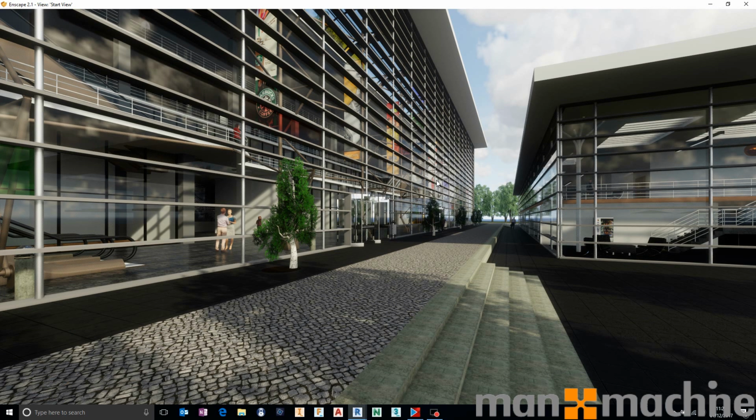Those of you that have used things like 3ds Max or Maya before and are more aligned with making bump maps, making normal maps, changing the lights, working with the photometric properties of the lights, we do all that inside of Revit. We just use Revit's default functionality to add normal maps, add bump maps, change the photometric properties of a light, and Enscape will just read those and it will just work with them. So have confidence that it can give you a very good result, and it can give you that very good result extremely quickly.